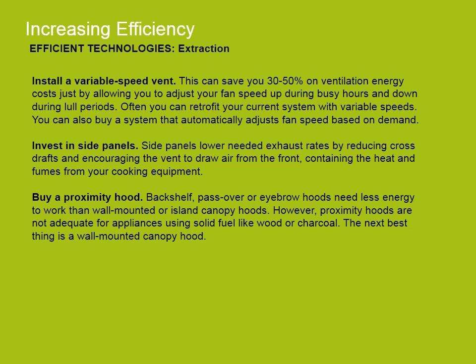Side panels lower needed exhaust rates by reducing cross drafts and encouraging the vent to draw air from the front, containing the heat and fumes from your cooking equipment. Backshelf, passover, or eyebrow hoods need less energy to work than wall-mounted or island canopy hoods. However, proximity hoods are not adequate for appliances using solid fuel like wood or charcoal. The next best thing is a wall-mounted canopy hood.